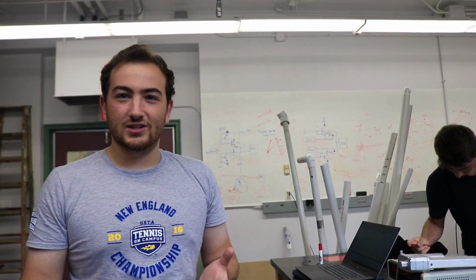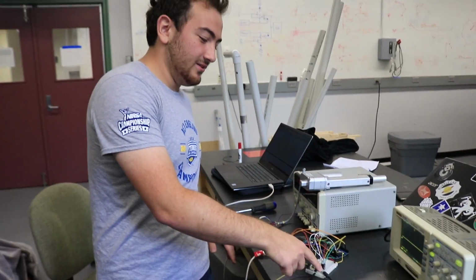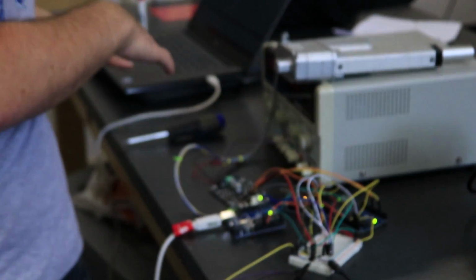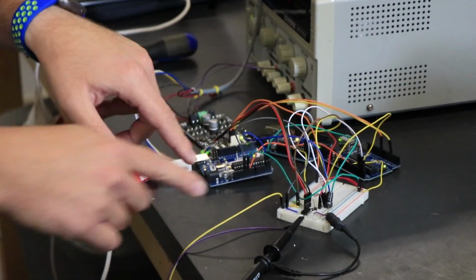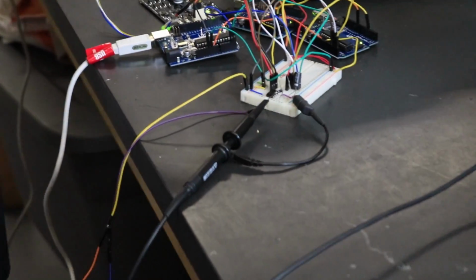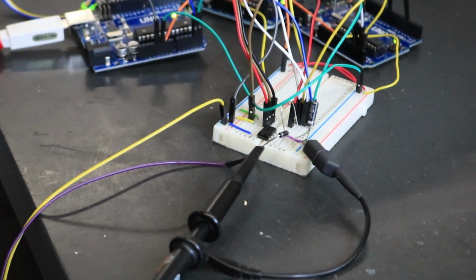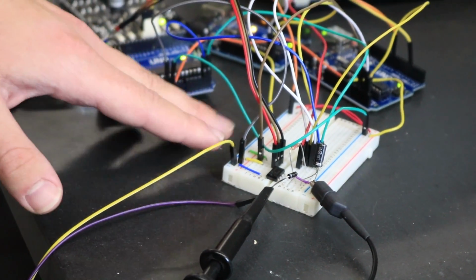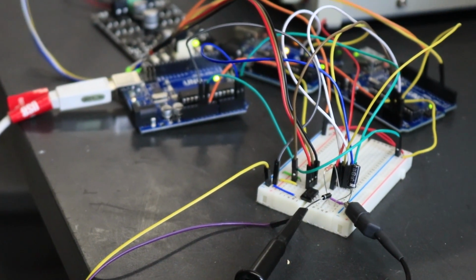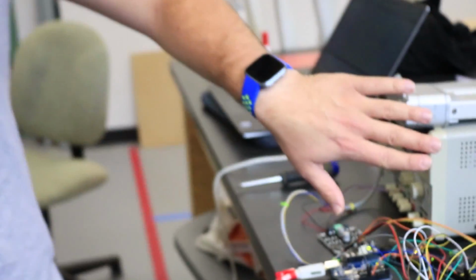So how do you differentiate between autonomous control and manual control? I'm glad you asked. Well, we're working on it. Basically what I've done is I've taken a diode here, which isolates my circuitry from the car circuitry. Diodes are cool because they allow current to flow one way and do not allow current to flow the other way. So whatever voltage and current is happening on one side, basically if the pedal is pushed, that doesn't screw up our circuitry here for autonomous.